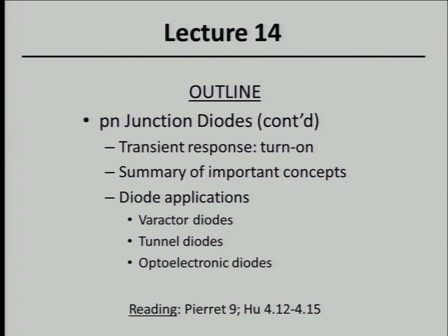In other words, how long does it take to build up the excess minority carrier charge concentrations in the quasi-neutral regions? Then I'll summarize all of the important concepts that you should know about diodes as we go forward. Because later when we look at the optoelectronic diodes and the bipolar junction transistor, you'll need to know these basic concepts for the PN junction diode. And then finally, we'll end the lecture today looking at common applications of PN junction diodes.